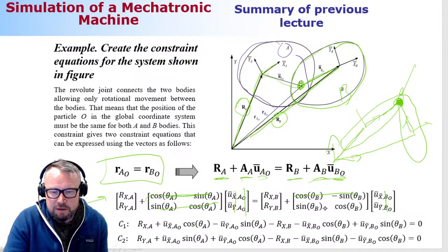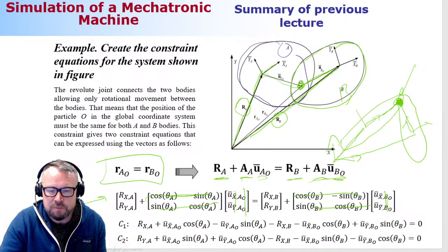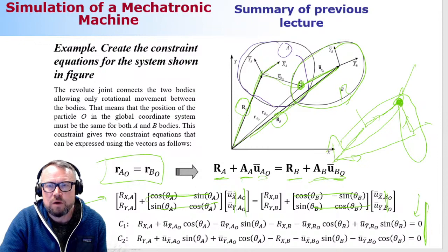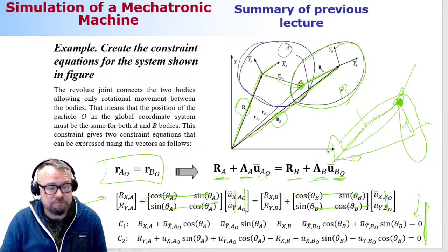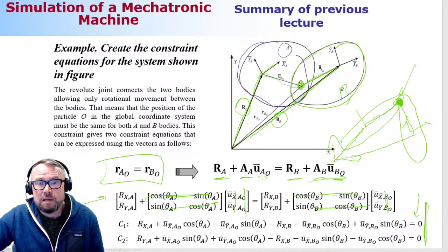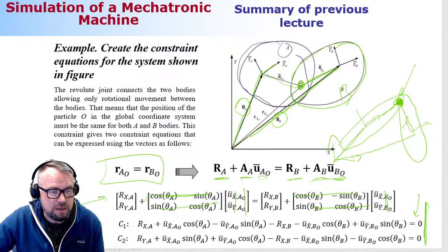And you do the same here. You have vector plus vector, you're multiplying the vectors, you're moving everything to the left-hand side of the equation, and this is your constraint, saying that the difference between these two vectors has to be 0 no matter what. That's your revolute joint. So it's very simple, very simple. And that's how we can make other types of constraints as well.